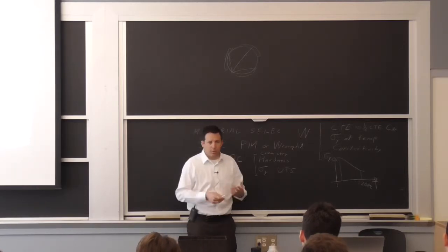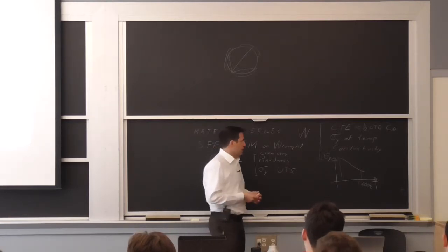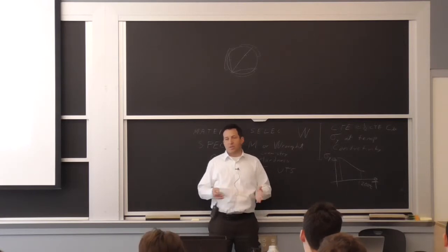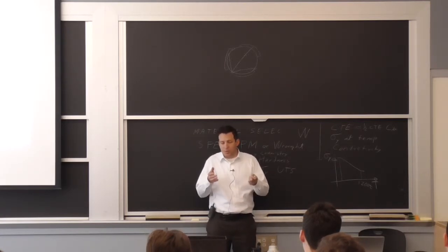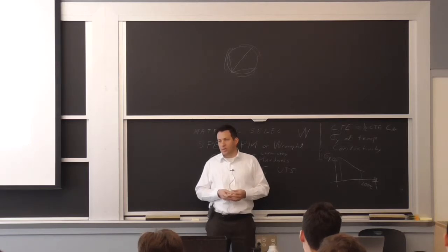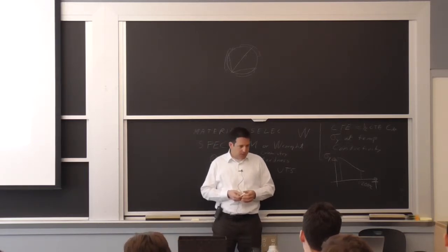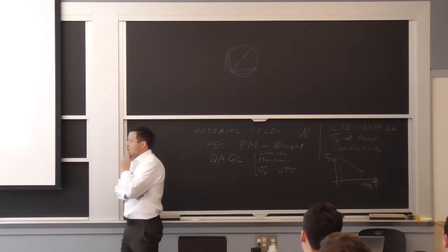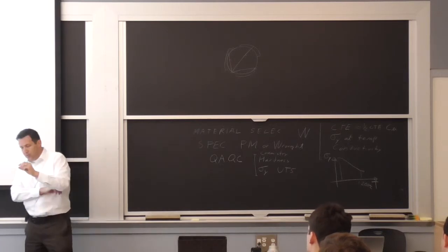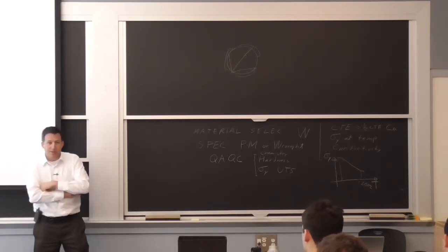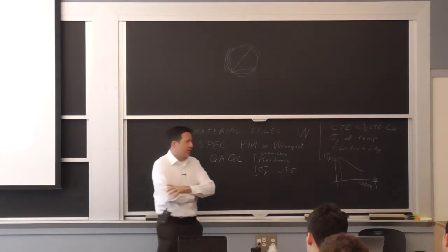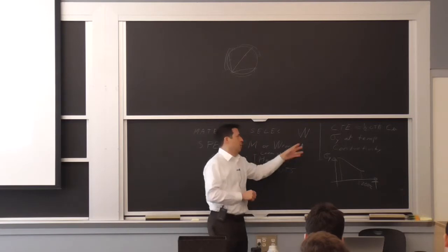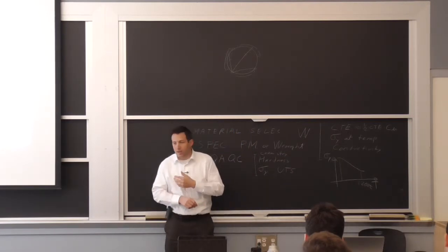You could have used aluminum, you could have used other things under here, but the copper was doing the work very well because even though it was not getting as hot, it was expanding and was compatible with the little tungsten layer. The tungsten here was only less than a millimeter, so it wasn't, again, a very large quantity of material, maybe 8 millimeter in diameter. That's all you needed. So you would be willing to spend a little bit more money on your material and your process here to avoid this cracking.